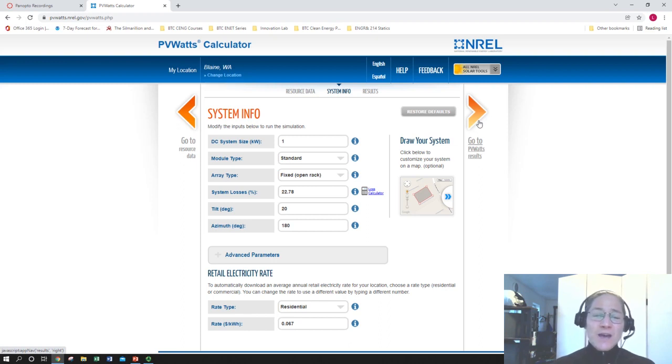So this person might be looking at, do they want to put more money into more battery storage or into a larger photovoltaic array that can recharge a fewer number of batteries faster? So do you want to go with generation rate capability, or do you want to go with more storage? So understanding how much electrical energy you can produce in the winter when you would be using this system is important in understanding how to make that call for your system.